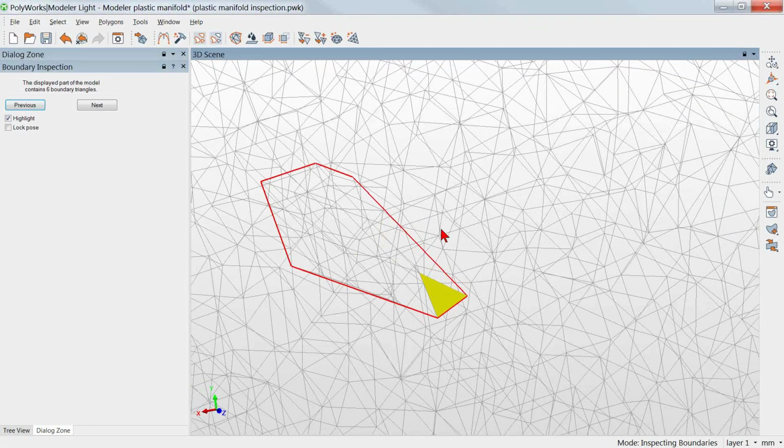So if I was in Inspect and I did a surface profile, I may get an anomalous reading in here where I've got some triangles that are below the surface, or they're really small and I can't see them because my model is really big. Well, in this case, this is the command where we're analyzing for the boundaries. It will go through and show you if you have anything in there.